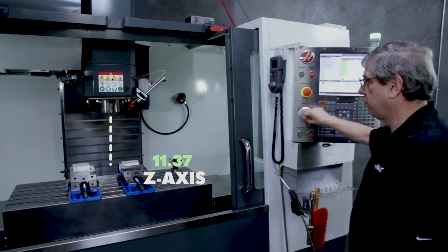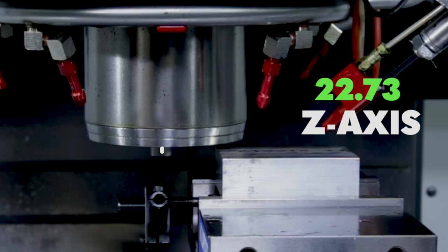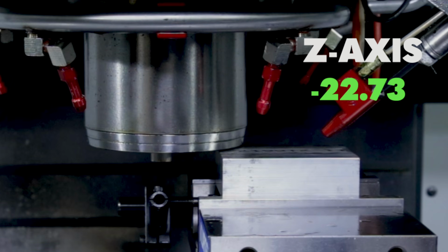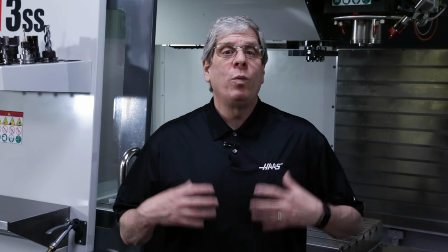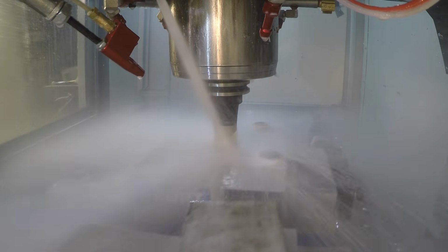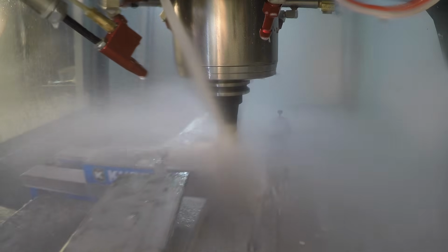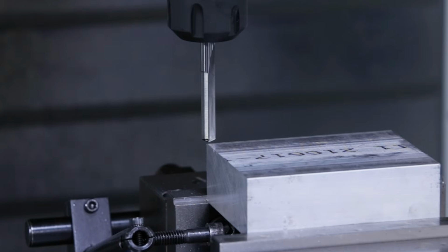We've also told the machine that our z-axis work offset is minus 22.73 inches away from z-axis home position. These 3 offset numbers give the machine its starting position for where we will move before it begins machining the part. But that's only half of what our machine needs to know before it can get started. What's the other thing the machine needs to know? Where is our cutting tool compared to home position? Or more specifically, where is the tip of our cutting tool compared to the tip of the spindle.